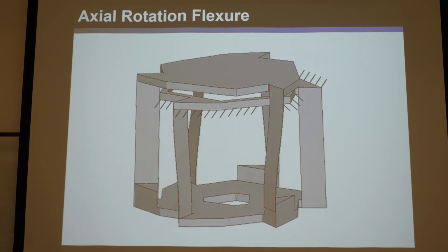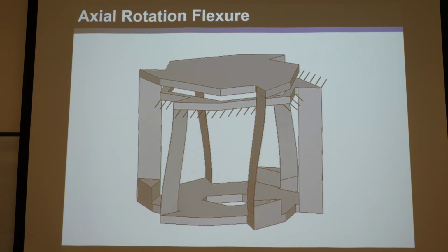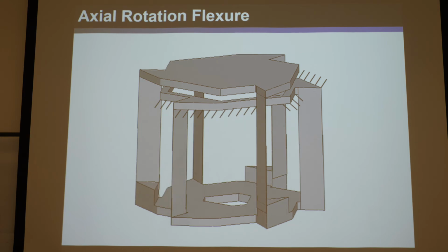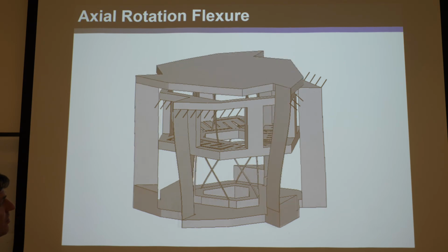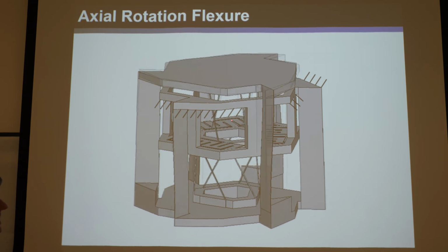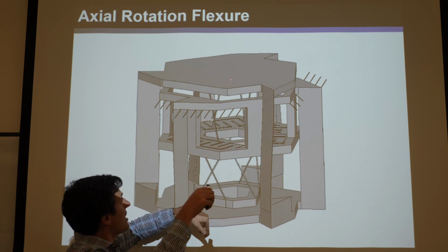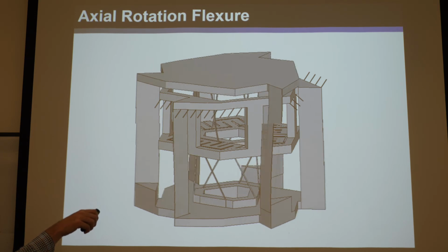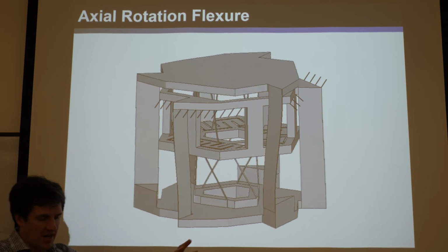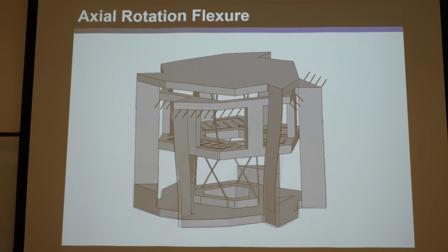But the problem is it's very under constrained. If you hold this fixed with respect to the ground, the stage, the intermediate body can now rotate uncontrolled. Okay, so what we need is an under constraint eliminator that's designed by FACT with screws in here to tune all the transmissions to be just right, so that as this central intermediate body translates, these guys are forced to rotate in a 2-to-1 ratio. And with this, we didn't increase the footprint. Everything's still nice. If we fix the stage with respect to the ground, everything, including all the bodies, will be locked up. Nothing's under constrained, and it forces the 2-to-1 ratio, so there's no parasitic error.